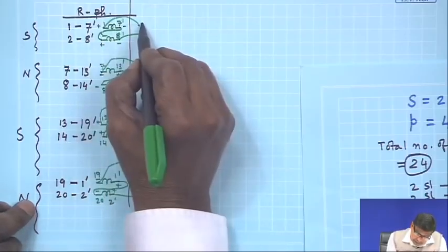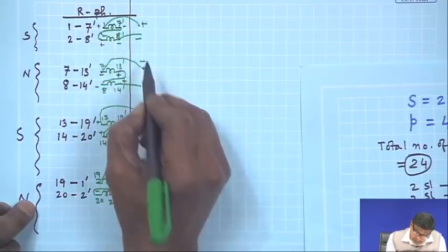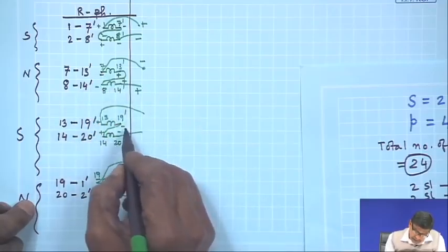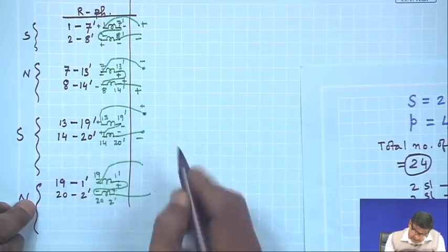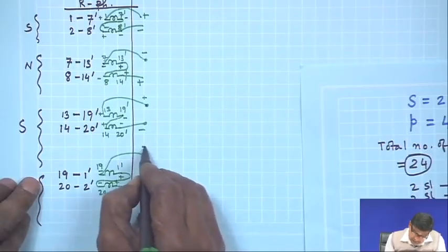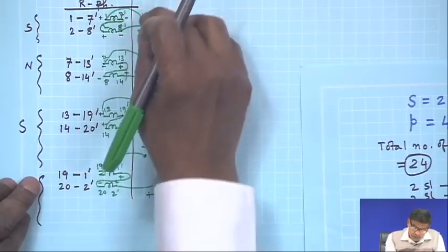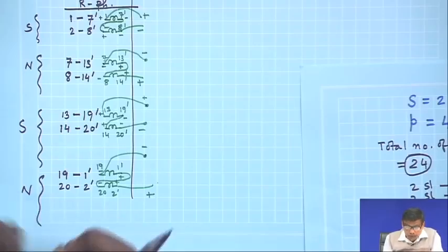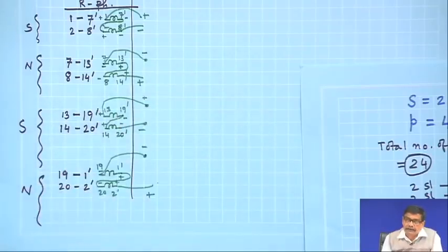So, if you see the polarity of the group, this is plus, this is minus, this is minus, this is plus, minus plus, minus plus, and once again this is plus, this is minus, and last one is minus, this is plus. Each group will have same RMS voltage. To have 2 terminals of the R phase, all these coils should be connected in series.